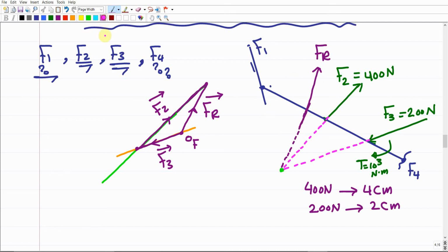So this FR can replace these two forces. Now we can cancel this force and cancel this force. So now we combine these two forces into just one equivalent force, which is this FR. This is the resultant force. So now we end up with a member of one force F1 at this end, another force at this end, and these two forces had been combined into one force, and there is one torque. Make sense? So this is how we can combine forces that are already fully defined, located in the middle of a member. We can combine them into an equivalent resultant force as already given here.